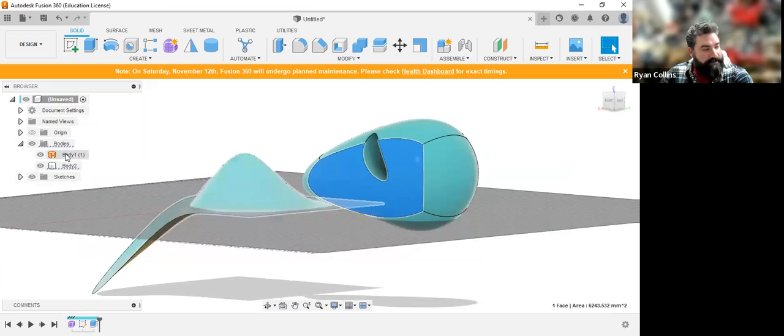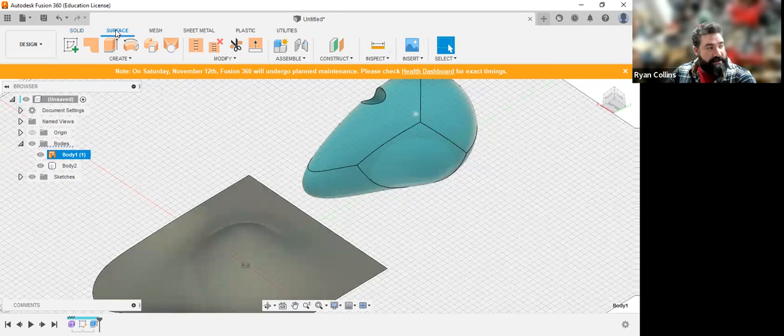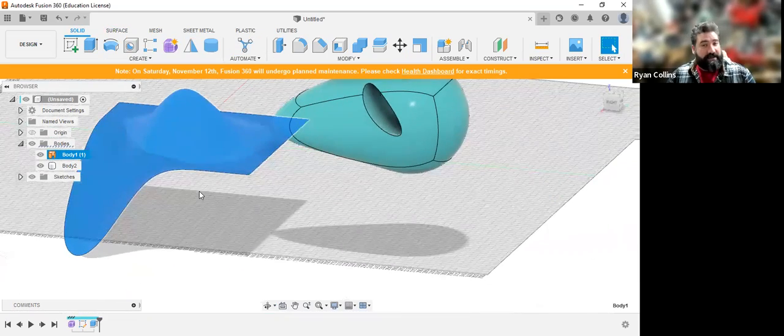However, the other one, the plane, is shown as this orange kind of foil wrap. That is showing it as a surface. Those are the color definitions on it. The reason for that is, although it is technically a three-dimensional object in that it goes up and down in the z-axis as well as x and y, it is only a plane thick. The best description for that is a non-zero thickness sheet of paper. So meaning it's anything above zero, but it has no real thickness to it.